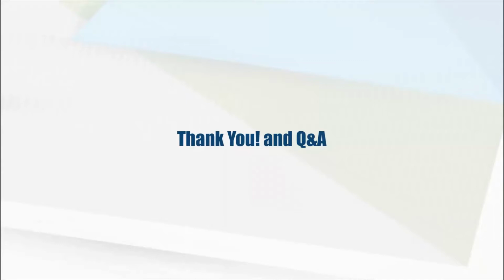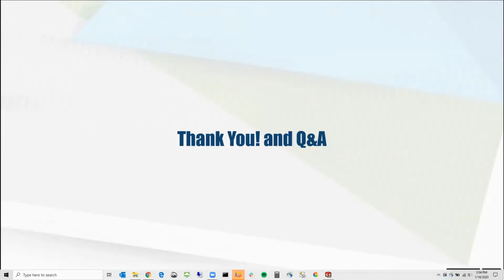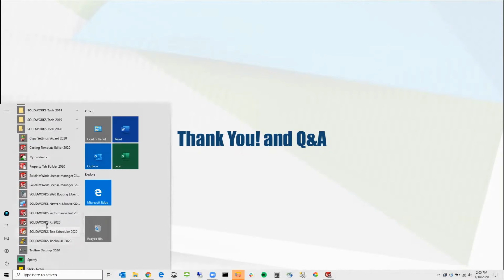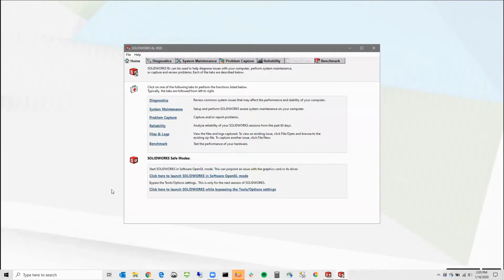Okay, his answer was using CPU diagnostics. They weren't able to find anything. The tech person didn't have a good answer. Sorry, that was going to be just due to an installation error where SOLIDWORKS was installed, and for whatever reason, it entered in the registry to limit the CPU cores. So that could be fixed with the SOLIDWORKS repair. Go ahead, Philip. What were you going to say?